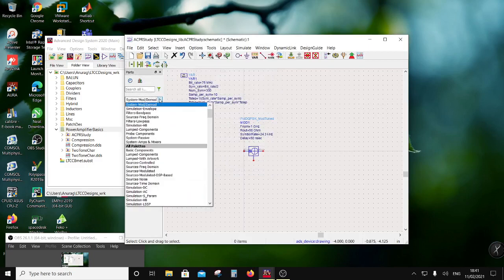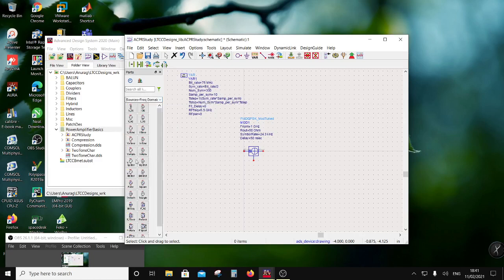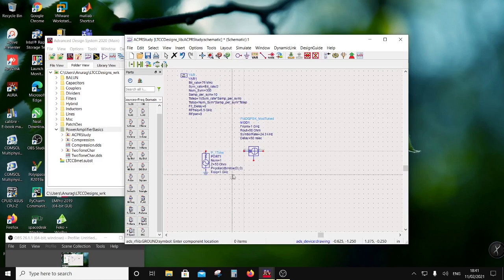So now I am going to put here a carrier source, which will be a P1 tone, right? So this will decide the carrier power and the carrier frequency, and I'm going to modulate that with a random number of bits, right? So here I am going to say that this frequency is RF FREQ, and sorry, RF power, RF PWR, and then the frequency is RF FREQ. Right, so we are set up with the carrier power and the carrier frequency.